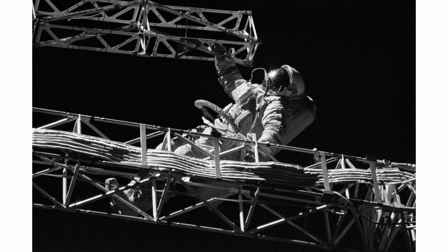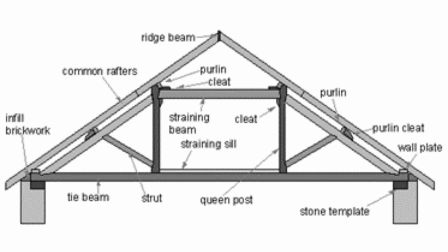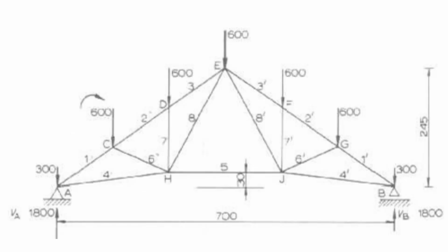Truss analysis and design is based on a certain number of definitions and assumptions, which distinguish trusses from beams and frames. By definition, a truss is a structure composed of slender members joined together at their ends. No member is taken to be continuous throughout a joint. Because members of a truss are slender, they cannot support significant transverse loads between joints. All loadings are considered to be applied to the joints.